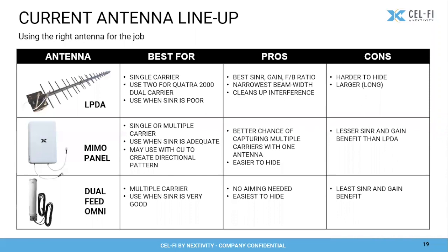So take your measurements when you're doing your site survey before you choose your antenna. And if it were my truck, I'd always have another option or 2 on the truck, because once you get up there and you actually install a system and take measurements from it, see what's going on, there's always a possibility you may have to change your mind on what antenna that you used, right? But the chances go down if you've done a good job of a site survey.